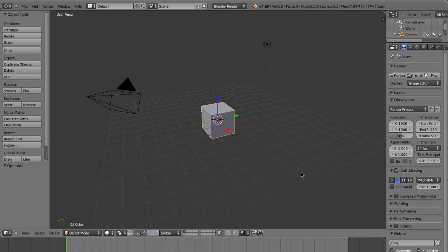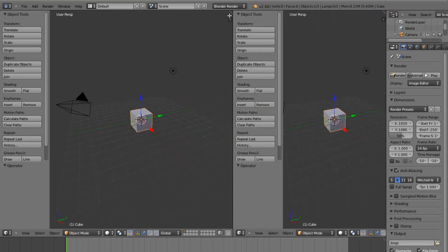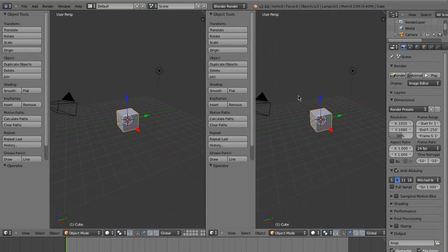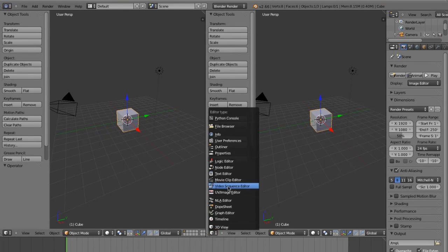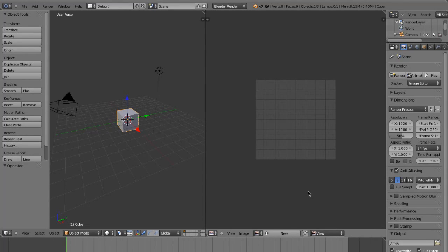Notice the diagonal lines in the upper right or bottom left corner of the panels. Your mouse cursor will turn into a cross when you hover. When you left-click and drag to an area, it becomes a new panel. You can then choose the panel type to your liking. To remove a newly created panel, click and drag on the same diagonal lines over an area of an adjacent panel until you see that area darken and an arrow symbol appears.